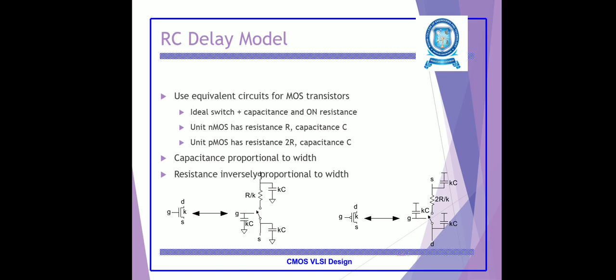In the linear region of the NMOS, VGS is greater than VTN and VDS is greater than 0 but very small. Then ID = μn COX (W/L)(VGS − VTN) VDS. Hence the Rn value is equal to 1 divided by μn COX (W/L)(VGS − VTN). For the triode region of the NMOS, VGS is greater than VTN and 0 < VDS < VGS − VTN.